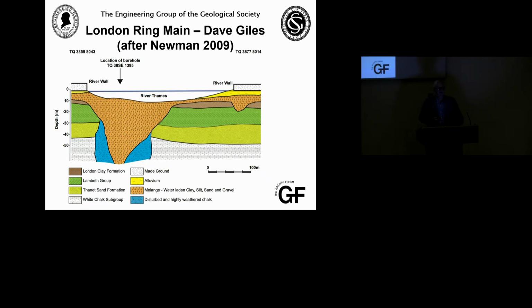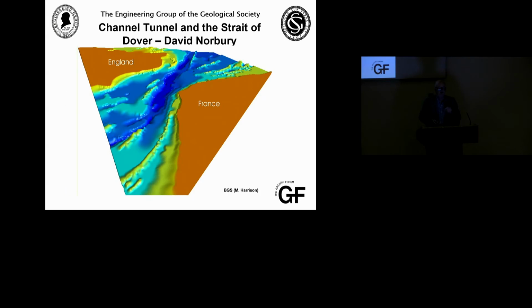And so we put in examples here that are still unknown in terms of their origins, about some of our quaternary structures. We're encountering these on our ground investigation and construction projects on an extremely frequent basis in London. The American Embassy down in Battersea had some interesting delays because it had to encounter some of these. The Olympic Velodrome out in East London was sat on top of one of these particular quaternary features. So we've got a significant geological hazard in a quaternary environment that we still really don't understand in terms of its genesis. Our ground model helps us understand that these could be predicted and starts to characterize what variability we might find within them.